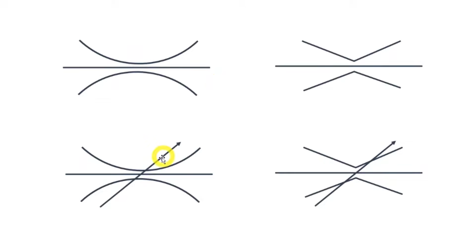These arrows on the hydraulic symbols indicate that the component behind the arrow is adjustable. This is the case for a lot of hydraulic symbols, such as adjustable pumps, motors, valves and such like. So this is a valve that is DP dependent and viscosity dependent, and it is also adjustable. I believe that this is the most common type of choke valve prevalent in hydraulic systems.